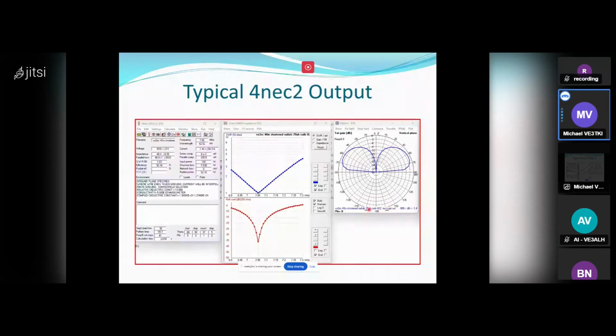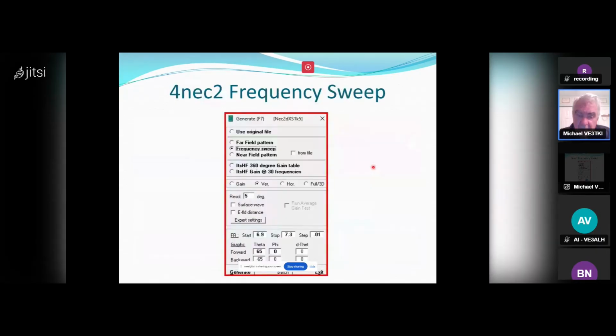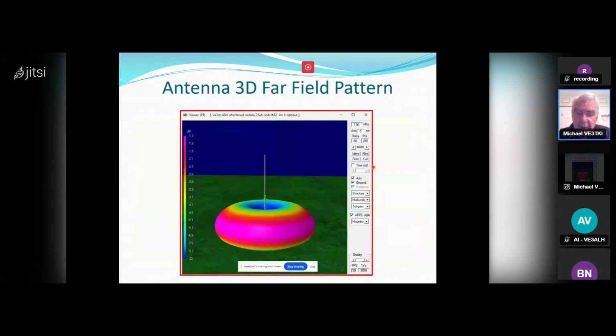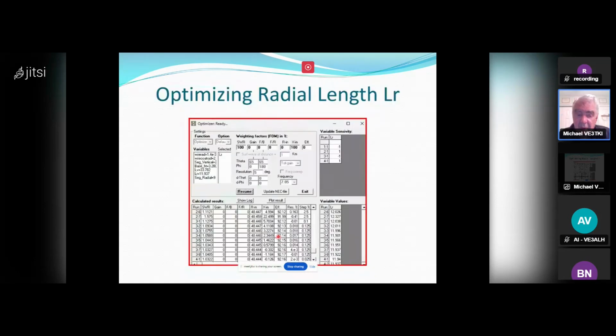And this is a cross section of the antenna. The vertical axis is here, so the vertical antenna is here. So it tells you it's got nice lobes around it. Then you can get a 3D representation of the antenna, and the red is the maximum gain, and it's symmetrical, so it's the same in all directions around it. And if it was a Yagi, it would look different.